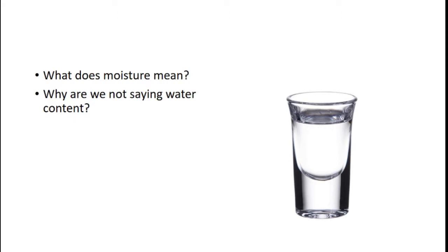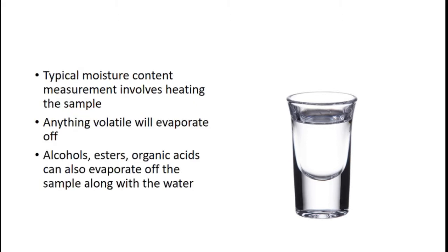Moisture is not just water. It includes anything else that is going to evaporate off during the heating process used for measuring moisture content. So anything that is volatile, alcohols, esters, organic acids, anything that can evaporate off the sample during the heating process is going to be measured as moisture content. And so again, alcohol is not water, esters are not water. So we do not say water content, we say moisture content, and that generalizes anything volatile.